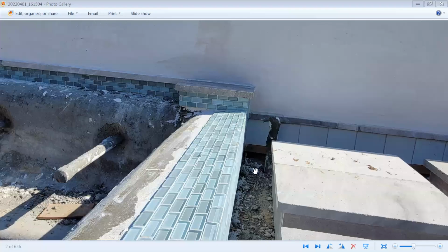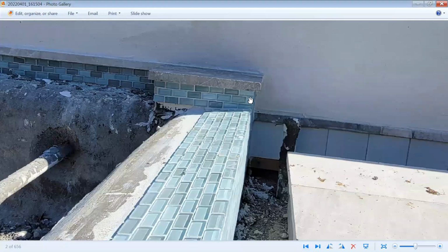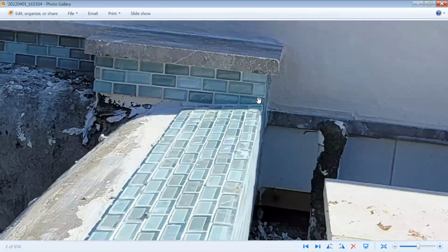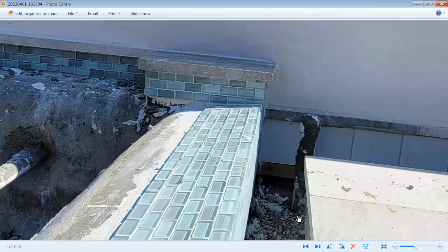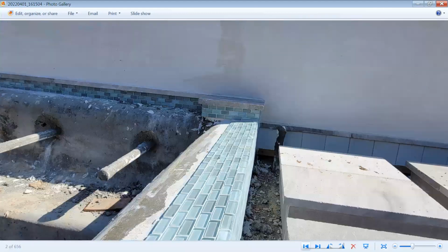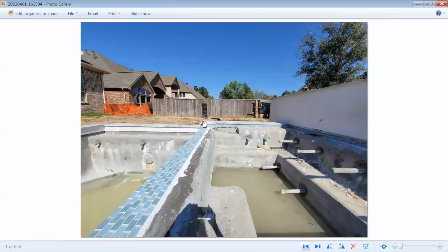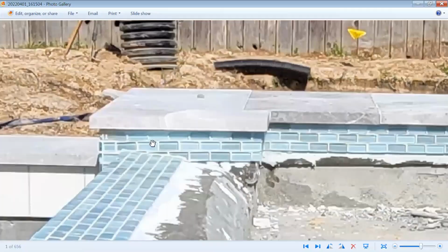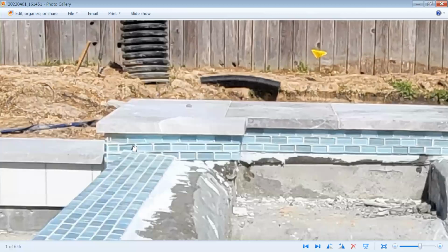In this particular pool, this is really not a waterproof vessel. I can tell you that by the way the tiler has put on some of the waterproofing membrane just underneath the glass. But if you look at this spa spillway and you look here at 1 inch, 2 inch, 2.5 inch, this is a perfect example of sometimes what tilers will do. And then take a look at this side and you'll see there is 1.5 or thereabouts, 1 3/4 glass tile.